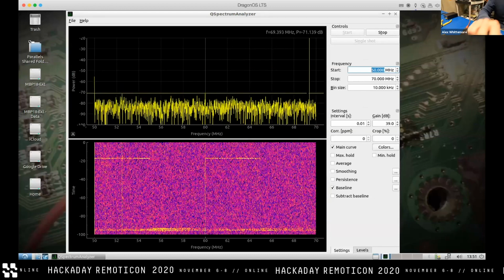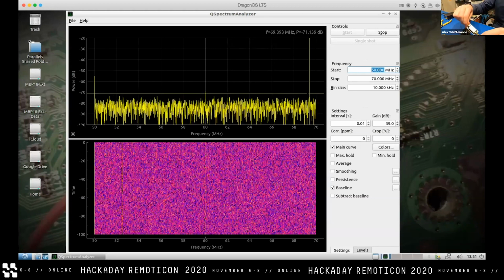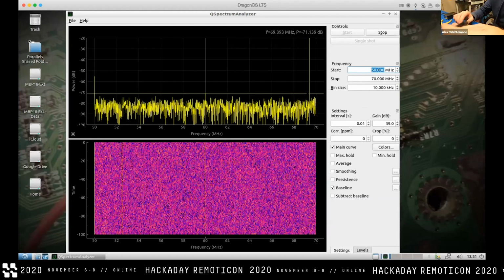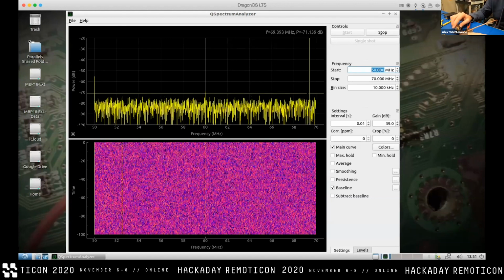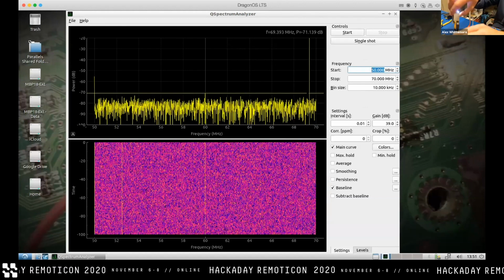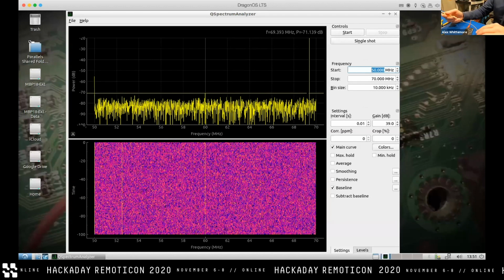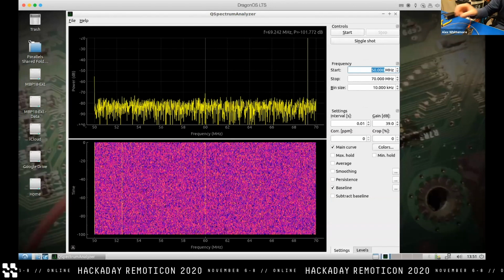Nice spot. And actually, a secondary point, because the HackRF does not have a bias T built in, we're going to have to power the LNA from an external source to make it even turn on. So that makes things more interesting. It also, did I click?